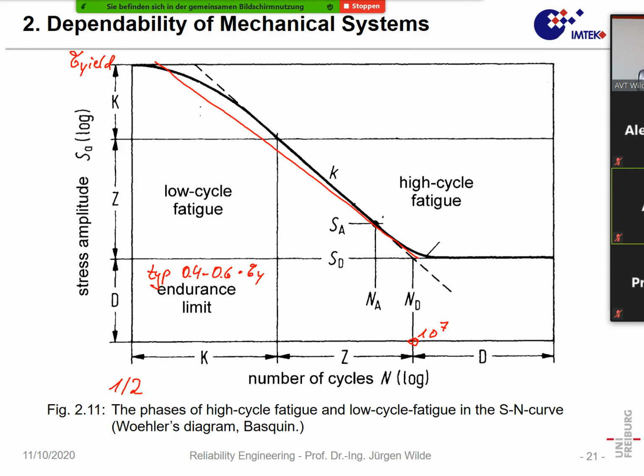And in that way, we can construct such a Basquin curve for a material where we have no more information. For instance, such a thing I would do maybe for a steel or for another material, but it is also important that we know the material really has an endurance limit.